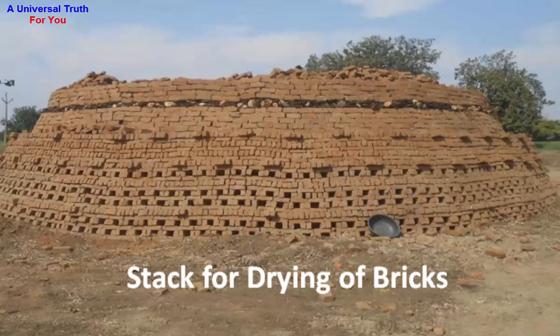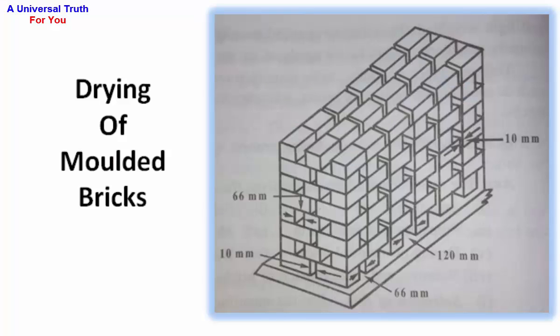This is the actual figure of stake for drying of bricks. You can look at it in this picture. This is the brick stake for drying purpose. And this is the graphical representation of drying of molded bricks. You can look at the gap between the bricks. This is 10 mm. This is 120 mm. This is 66 mm. This is 10 mm. And this is 66 mm.